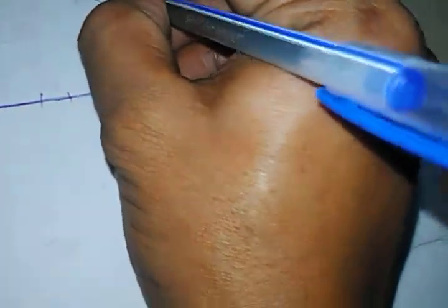And what is the last point? The imaginary axis crossover point we have already mentioned. The last one is the angle of departure. The angle of departure we have found out as minus 36.94 degrees for the pole at minus 3 minus j4. So I draw it here. Here also you can draw the angle using a protractor, and since it is minus, we have to draw it on the negative side. I am just using a protractor to draw the angle. This angle is minus 36.94 degrees. Similarly for the second pole, at minus 3 plus j4, the angle will be positive, 36.94 degrees.